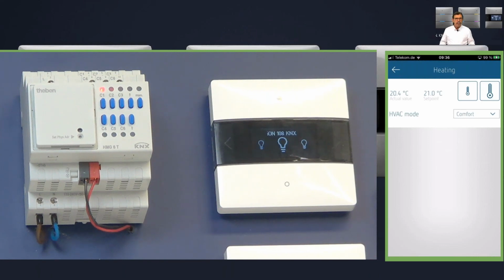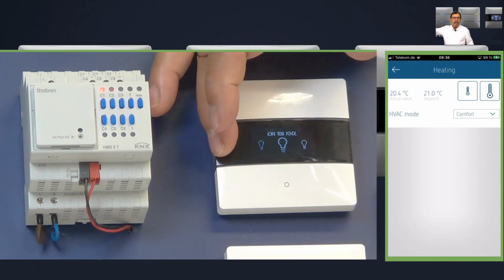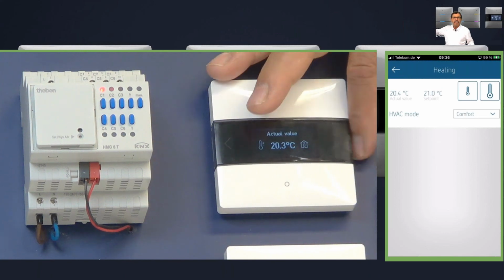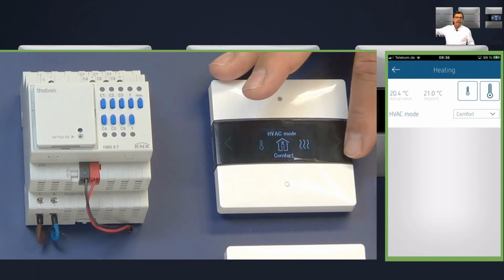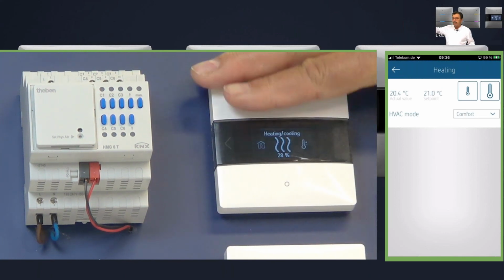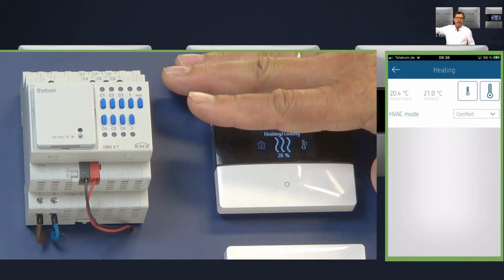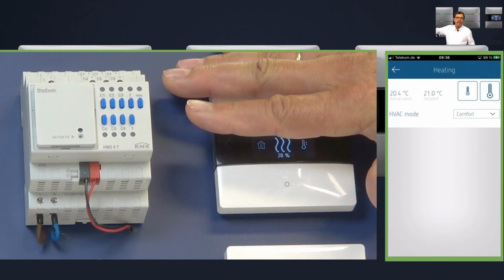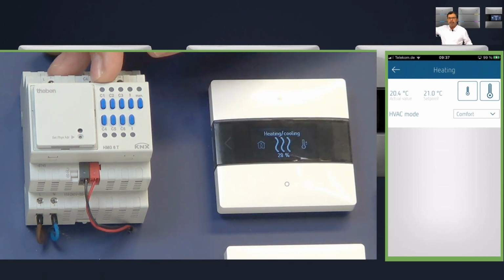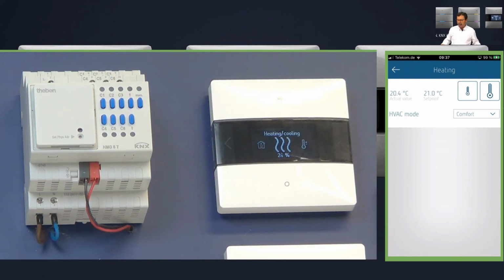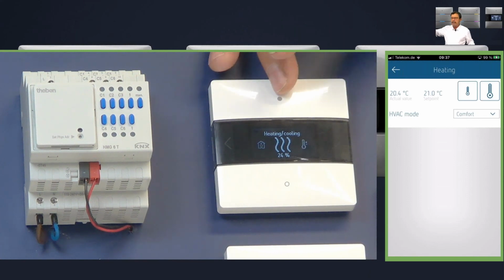And due to that, we have a rather small value of the control command finally, which is 28%. Probably if I put my hands for a couple of seconds upon it, this value will definitively reduce. It must, because the heating actuator even has switched off. So there's a short delay time nevertheless. And you see now 24 degrees. So we come closer to our desired temperature, and that's it.